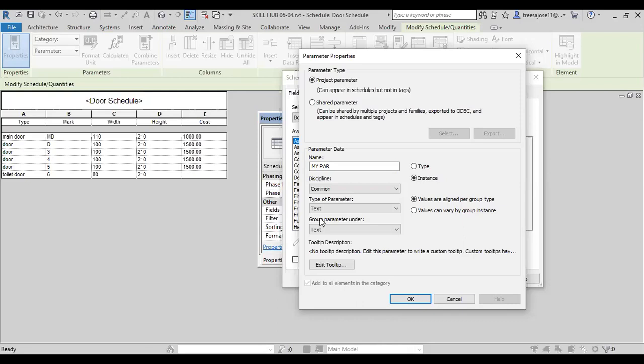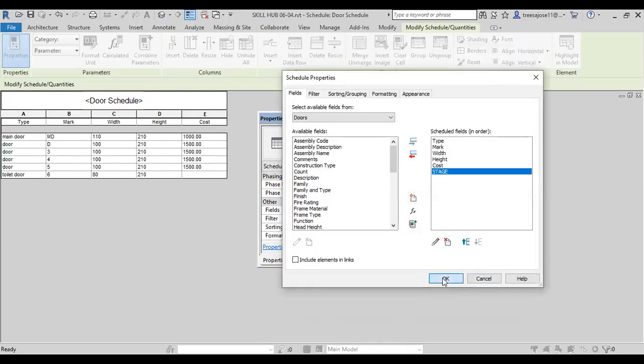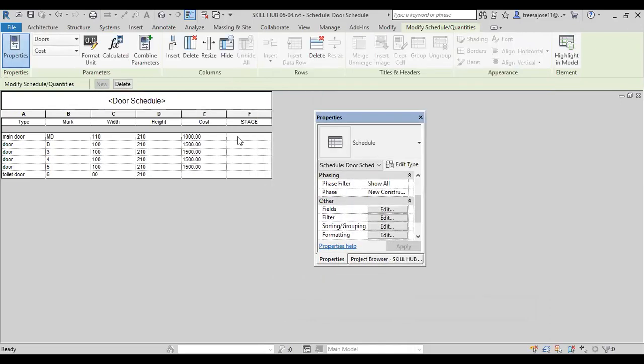Keep that in mind. You have to select the type. For example, for the stage of work, or finished, or yes or no, you have to put text only. That time you set the parameter type as text, not as integer or something. For integers, that field will take numbers only. Then okay. Automatically that will be here. If you try to input that, the text type will take numbers and text. Integers will not take text.